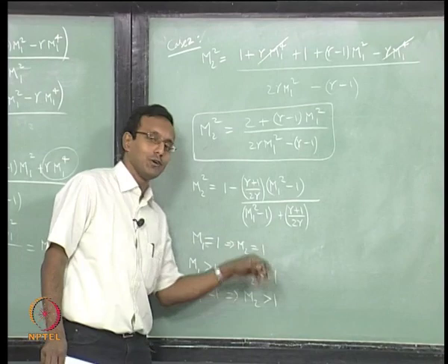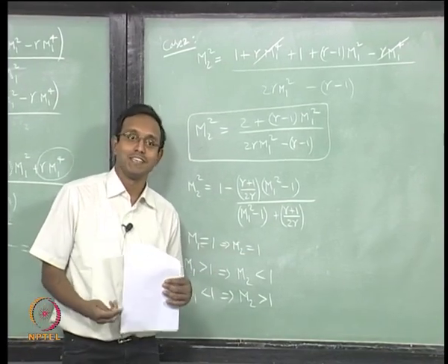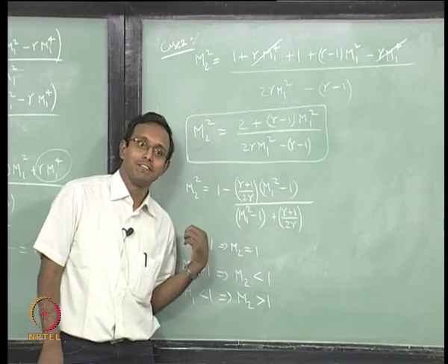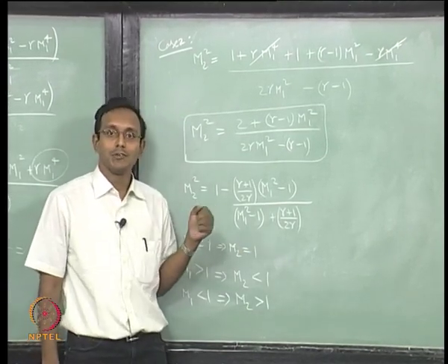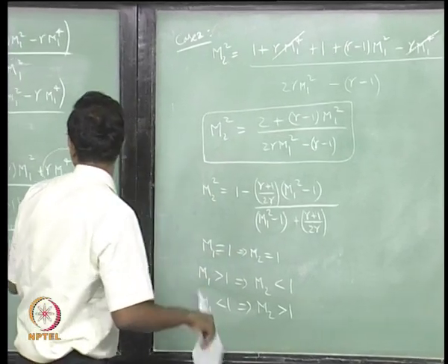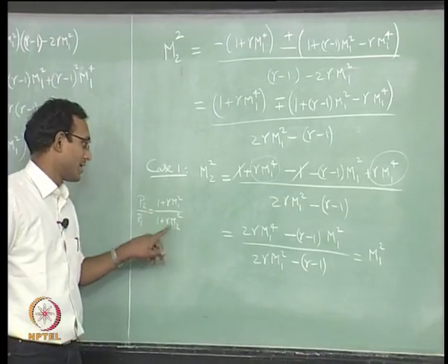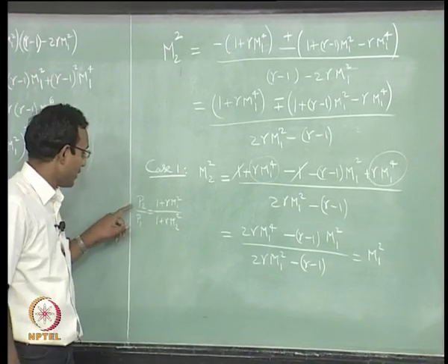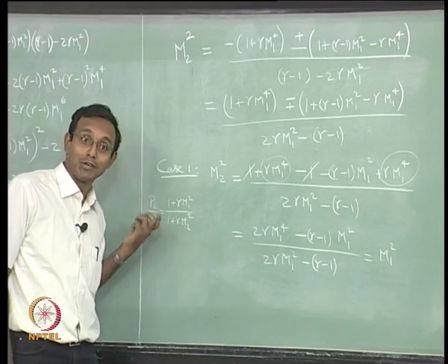m1 equal to 1, m2 equal to 1 is not any great solution, it is just your Mach wave. Why do I say that it is a Mach wave? That is a wave that is going through and it is going at speed of sound. One more thing I have to look at, it is here, we will go back here. If I look at m1 equal to 1 and m2 equal to 1, I am going to get p2 by p1 equal to 1, which means there is no change across that particular wave.